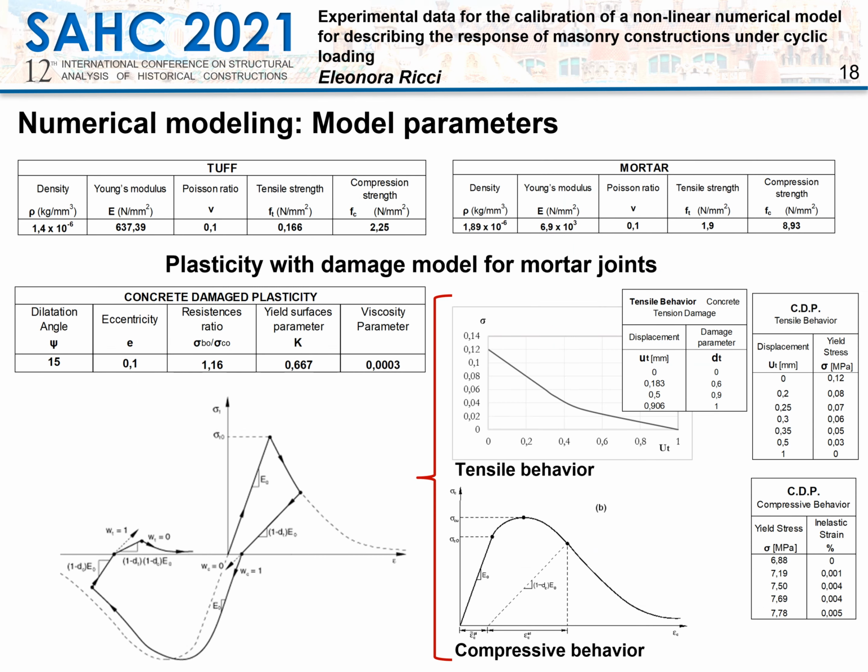The experimental data have been employed for calibrating a numerical model of the arch, developed in Abaqus, capable of simulating the cyclic behavior observed in the test. We modeled separately masonry blocks as linear elastic and mortar joints, where all the nonlinearities were supposed to be concentrated. Mortar joints were described by the concrete damage plasticity. The behavior in compression was calibrated with reference to previous experimental studies performed by us on similar mortars.